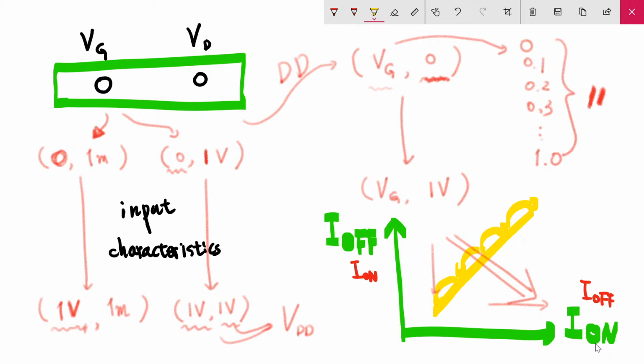So it means that, for example, let's stick to this green line. Yes, we are now having the on current as the x-axis and off current as the y-axis. Then if we move from this point to that point, what does it mean? We just reduce the performance. Performance simply means the on current, and by the sacrifice of our performance, we have better leakage characteristics. That is one thing. And the other way around in this direction is that, instead, I just